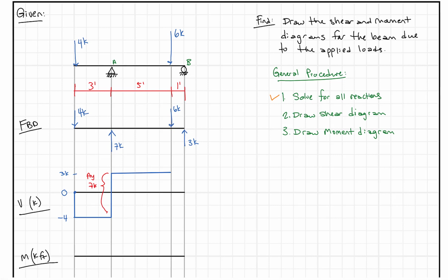Okay, so let's look at that. 3 kips, minus 6 kips. So if I draw that in here, this is going to be -6 kips, and that's like BY. So when we come down -6, we're going to get to a point over here that's -3 kips. And this is kind of cool because when we continue our shear diagram over to the 3 kips, let's look what happens. We bring it over, and you'll notice now we have a 3 kip force that's pushing us back up to 0. So we'll come right back up to 0. And when we do that, our shear diagram also closes.